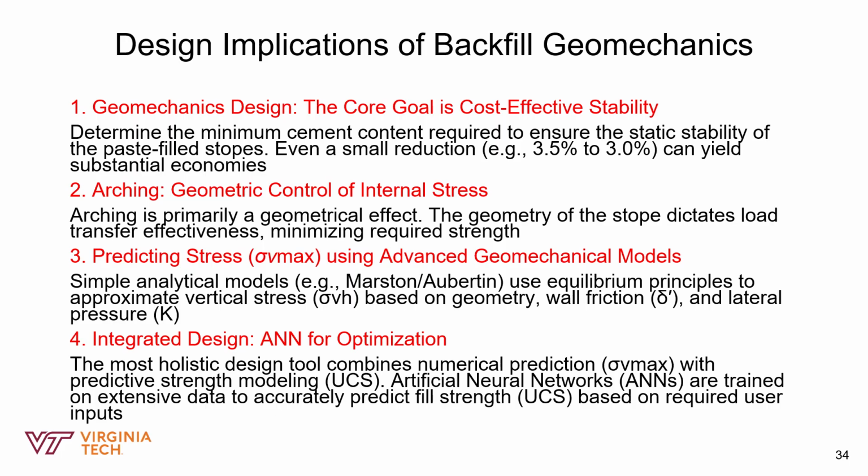The second point is incorporating arching as a tool. So we don't just hope for arching, we have to design for it. And by understanding the geometry, we can shape our stopes to maximize the natural load transfer to the walls. Also, predicting stress using advanced geomechanical models. So now we are not just doing guesswork, we are moving away from that. We are using analytical methods to predict exactly how much stress the backfill will face.